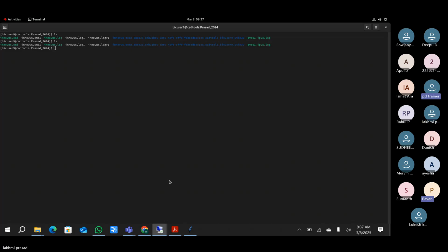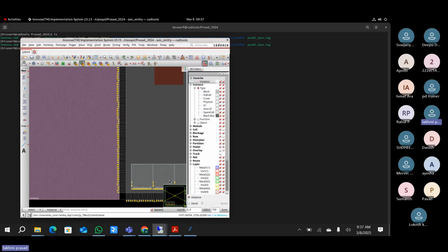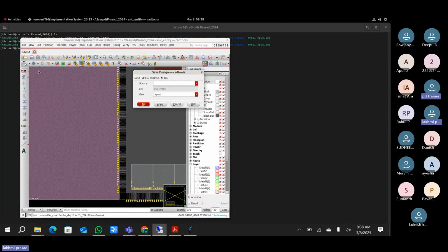Then how did you load Innovus? I have used an ampersand. That is the reason I think it got exited. Can you please tell me, restore this design actually? File, restore design, save this. To save this design, this is the way, right? Yeah, here, right click, select on Innovus, not OA. OA is the last one, it is the layout. OA means our GDS layout, final layout. So here, select on Innovus, file name, just give any file name .enc.